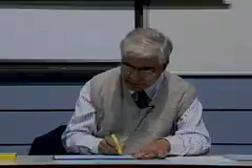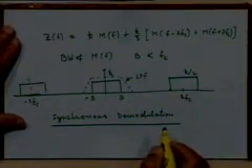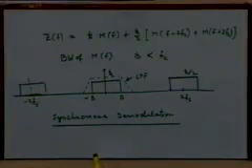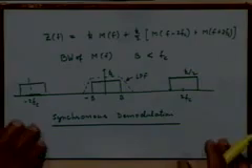So this kind of demodulation is called synchronous demodulation, whereby we imply that the demodulating signal, the local carrier at the receiver, should be in perfect phase and frequency synchronism with the carrier of the received signal, right? Because if it is not so, we will not get a perfect demodulation. Let's see why, right? So let's look at the effect of loss of synchronization. If your synchronization is not perfect, what will happen?